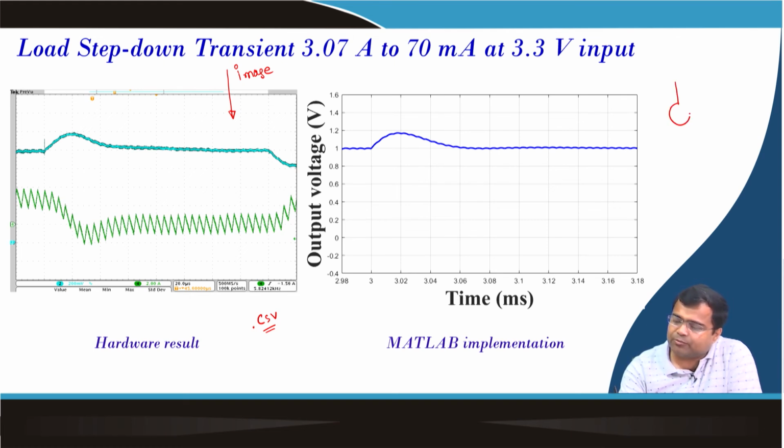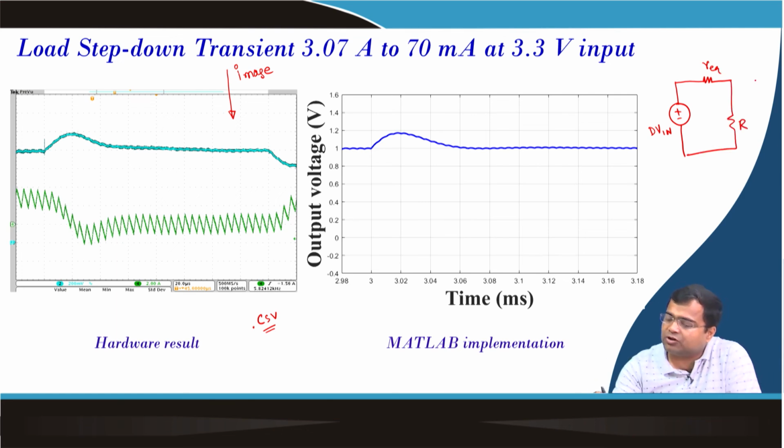Because if we get the equivalent DC model, right. So, the DC equivalent model, we have discussed this DC equivalent model D into V in, then we have to consider this R equivalent. Okay. So, output voltage will not be simply V 0, it is a DC equivalent circuit, because we need to consider this R equivalent, and this R equivalent is nothing but inductor DCR plus R on.